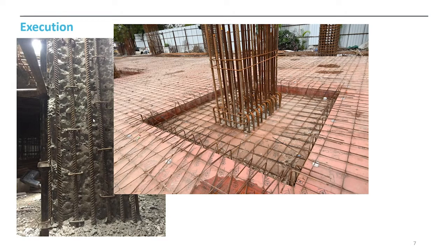At some other place, this was the ground floor at that time, probably sometime during August or September last year. When the flooring concrete was yet to be poured, they drilled holes in the shuttering, provided the reinforcement in the vertical direction, and then poured it.